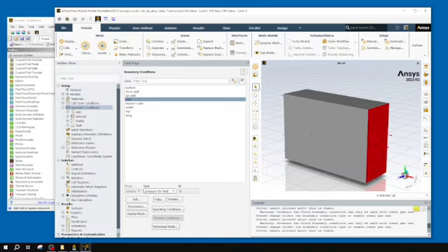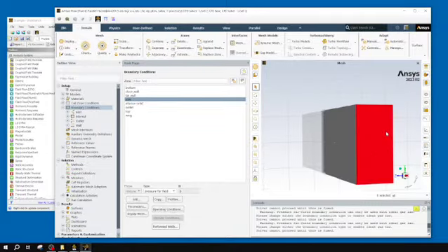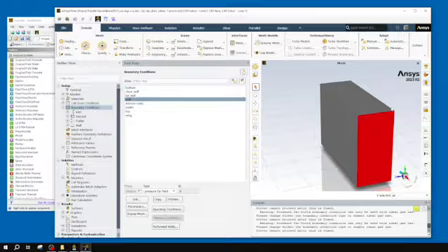I would use more the defaults of that wall and velocity inlet if I was simulating wind tunnel results. So that wind tunnel actually has kind of walls, top, bottom, and side, rather than kind of a far field. But since I'm considering this as a wing out in the real world, that's why I'm using these far fields.